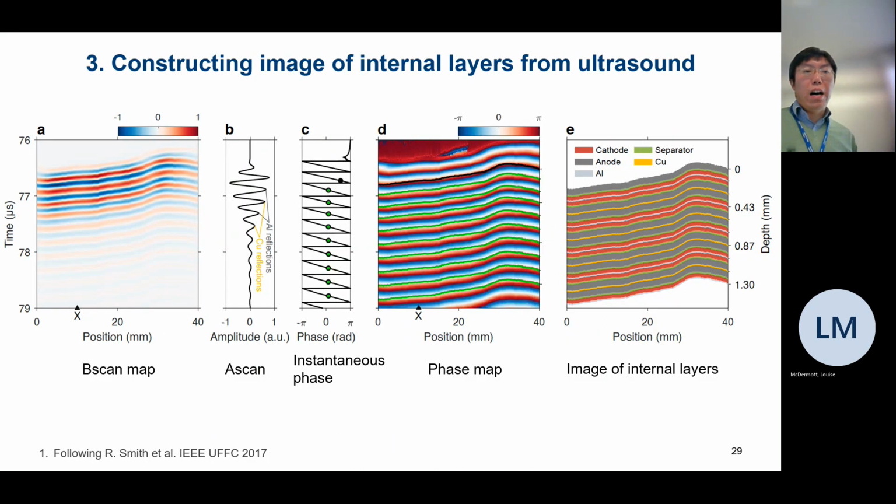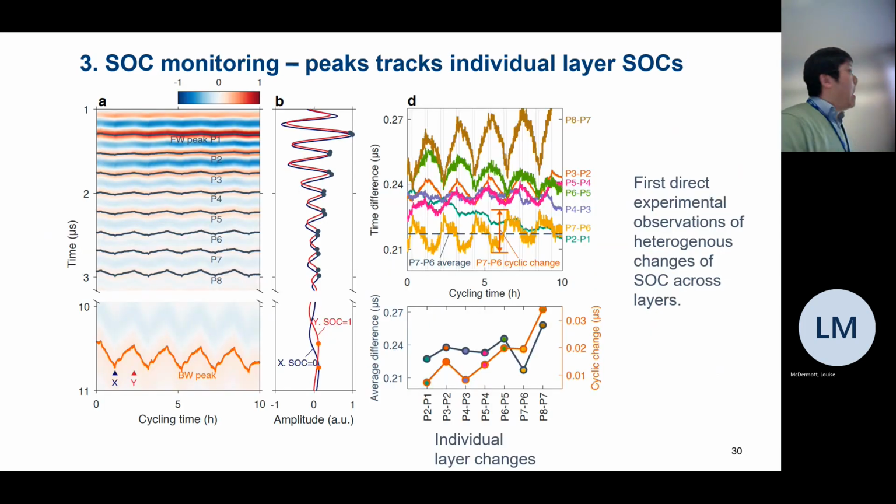And because we have the capability of tracking the internal metal layers from these resonance peaks, the differences between each peak give you the property of a pair of electrodes. By using that, we're doing SOC, so basically the charge and discharging cycling process.